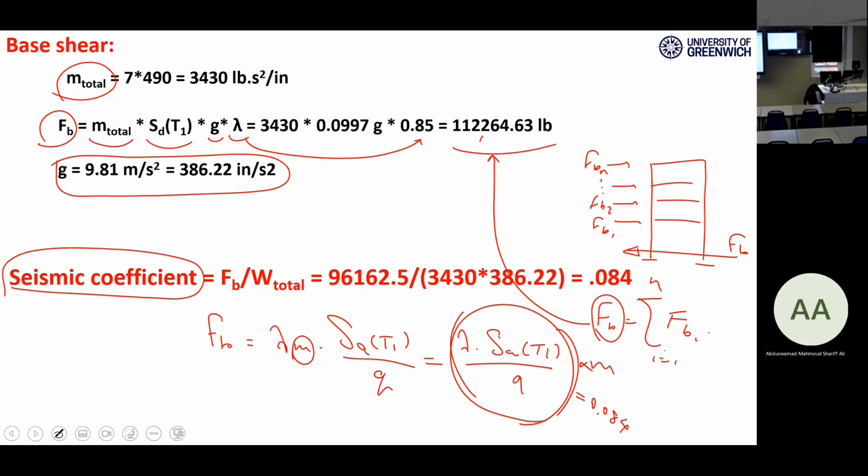They just mandated the designers in these earthquake-prone areas, because before that they just designed the structures for the gravity loads, only for the gravity loads. For the first time, they said, okay, in addition to the gravity load, we should put a horizontal force for the structures equal to 10% or 12% of the weight, in addition to the gravity. And it was the rule of practice in some of the states in the United States for the first time.